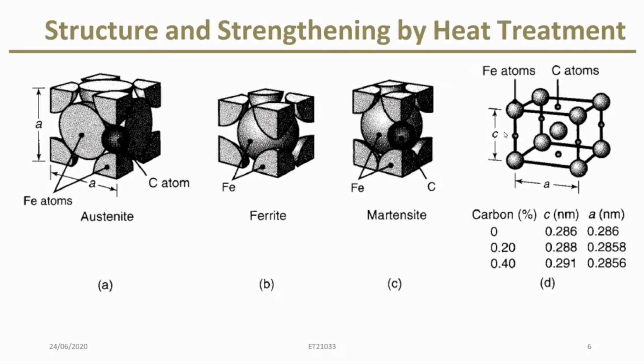If we want ferrite to be strong without losing its ductility, we rely on grain refinement, solid solution, or precipitation strengthening in the alloy, and cold working with stress relief when appropriate. Ferrite-rich structures provide stiffness and dimensional stability. They are two opposite ends of the dial from hardened martensitic structures.